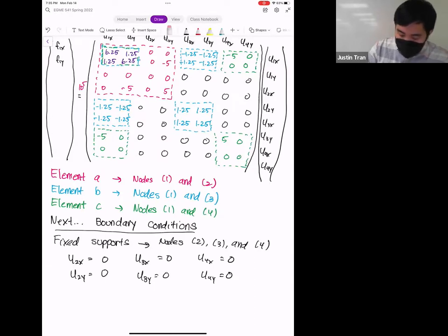And so we can go ahead and write those into the matrix. On the forcing vector on the other side of the equation, we have 0, 0, 0, 0, 0, 0. Remember, when we apply our Dirichlet boundary conditions, we replace the entire row of the matrix with the appropriate values. We replace the entire row with zeros. For this row, it's almost all zeros already. That should be this one.